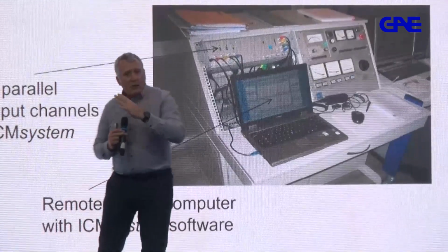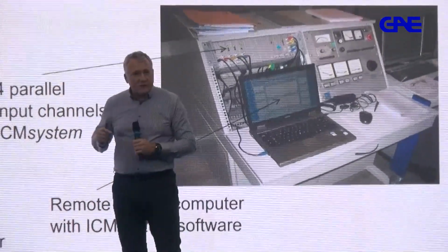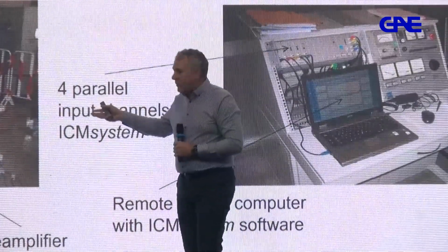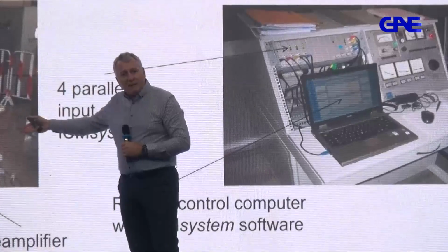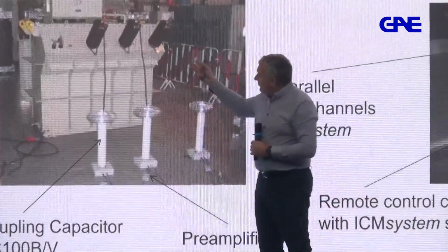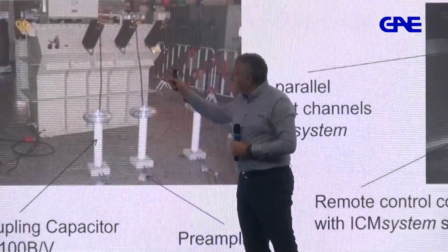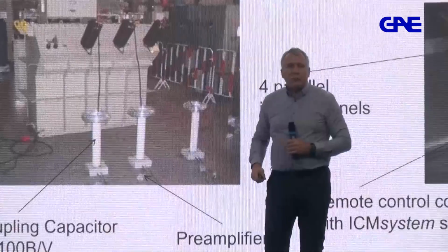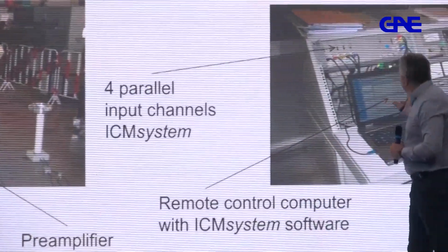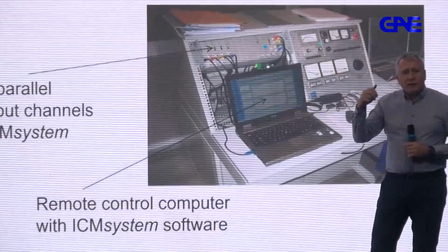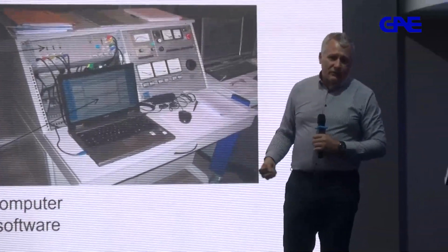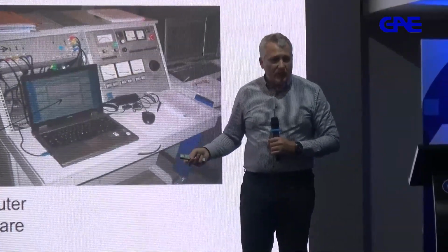Again, you have a test object, the distribution transformer. You find ways to receive the signals from this distribution transformer by means of such coupling capacitors, tuned with a certain voltage, generally to the high voltage side of the distribution transformer. And then you acquire that information, examine the partial discharge signatures, levels, and then you can say, okay, this was a well-manufactured transformer, well-repaired transformer, okay?